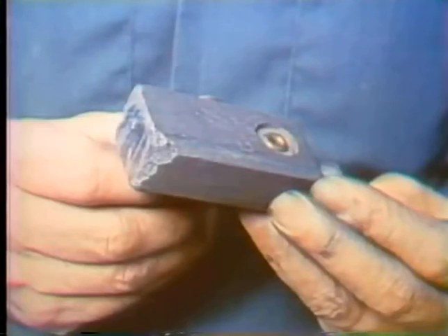You've also got a problem if the brush doesn't make full contact with the commutator. If the brush tension device is set wrong, there'll be trouble. Broken, cracked, or chipped brushes will also give you headaches. You see, the size of the brush is determined by how much current it has to carry. Cracks or chips reduce the surface area of the brush, so current has a smaller area to go through, and this causes sparking, arcing, and heats up the brushes. The same problems occur if the brushes aren't making full flat contact with the commutator.